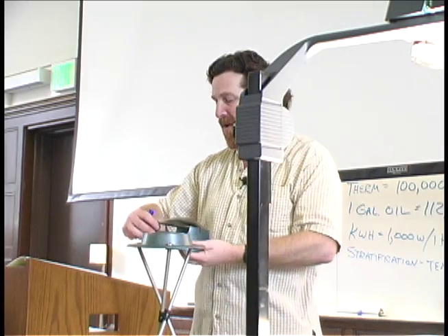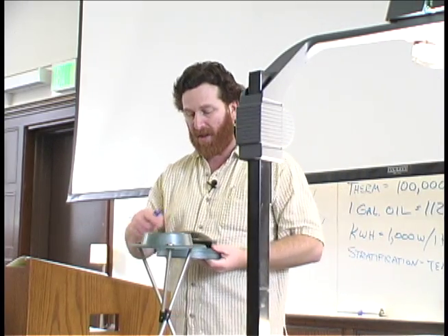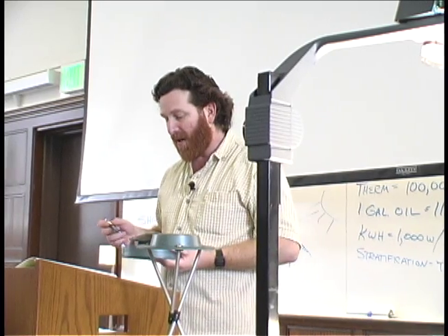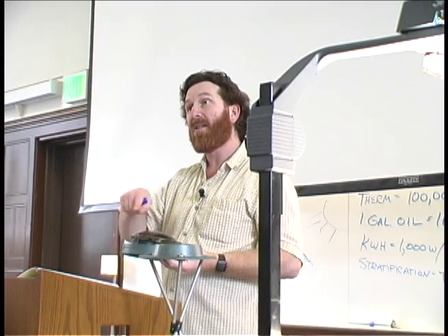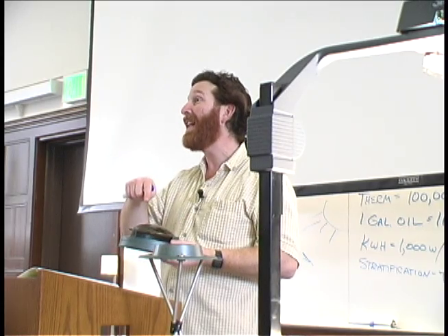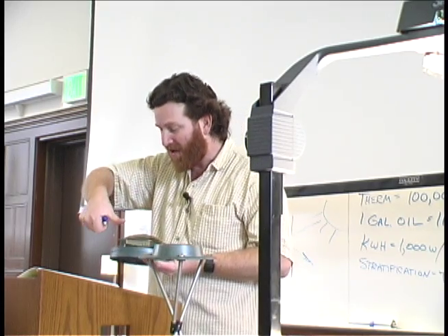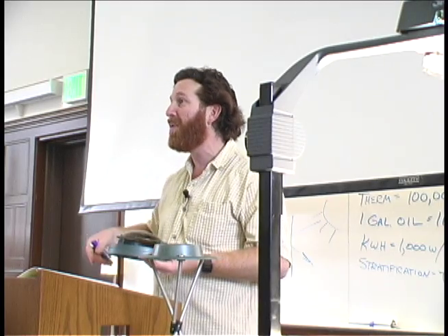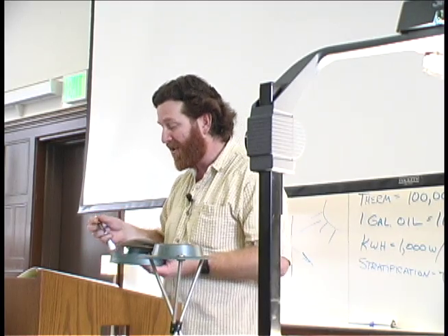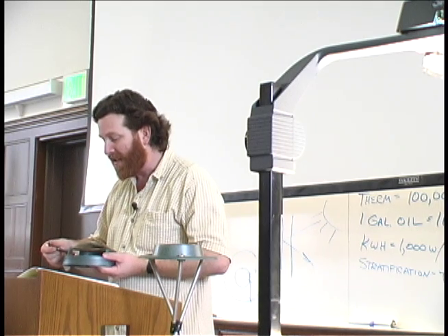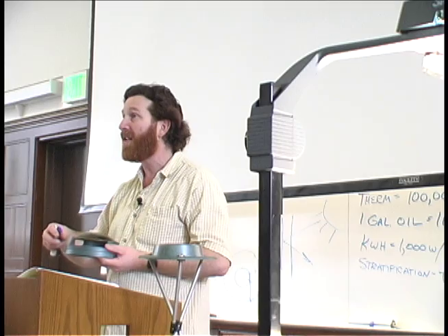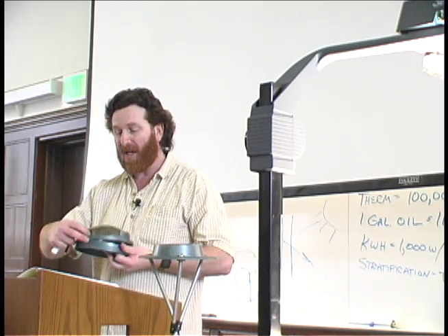And then you set the dome over it, and you put your face about 12 to 18 inches above it, and it mirrors the southern sky. So the best time to do this is on a cloudy day, because otherwise you've got the sun right there, and you've got to put your thumb over it so you're not blinding yourself. So it mirrors the southern sky, and then you take the grease pencil and you trace the trees and the buildings and any other shading that you've got at the site onto the sun path chart.